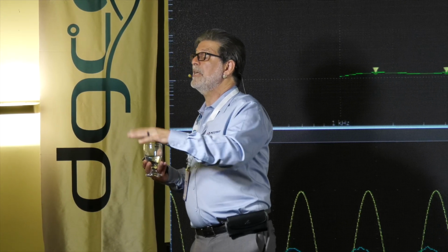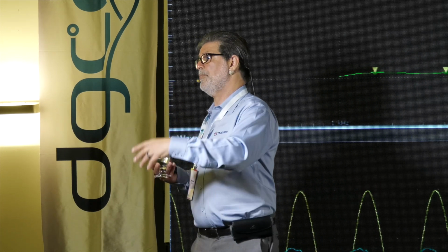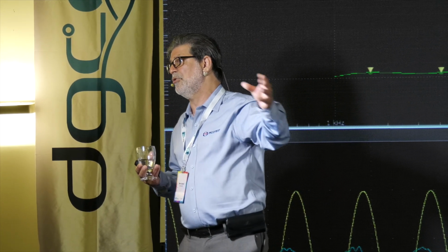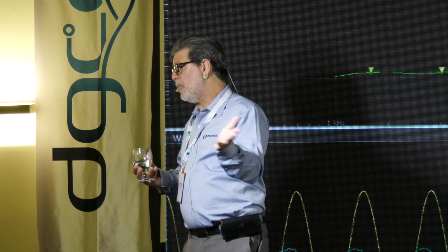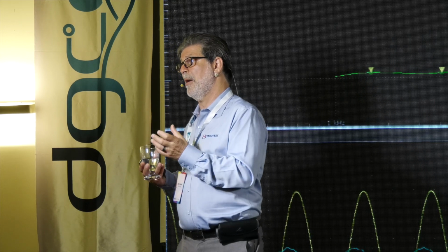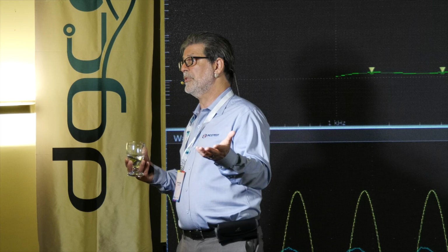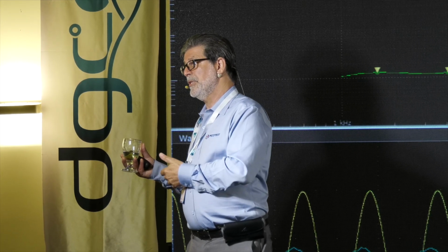Where do we need it to be? That's part of a budget. And that budget is made up of the voltage ripple, power supply rejection ratio transients, and dynamic current transients. And we can trade those off one for the other. Right? And that's what I had to do for Xilinx because they chose a power supply that had no controls other than the output filter and switching frequency.